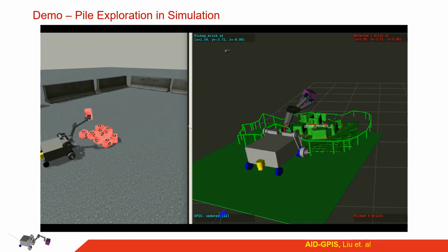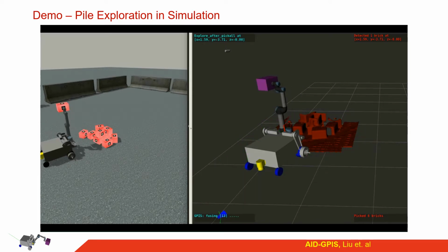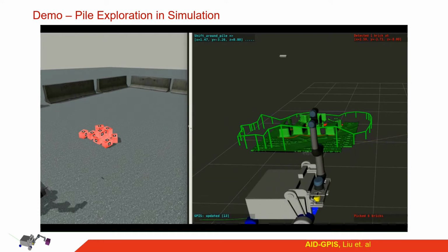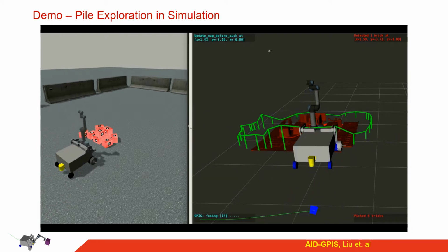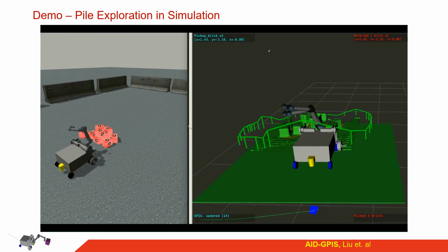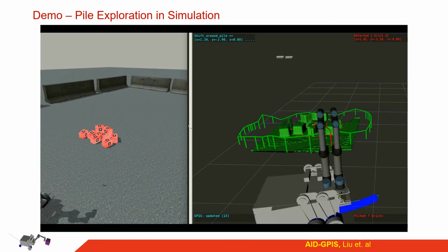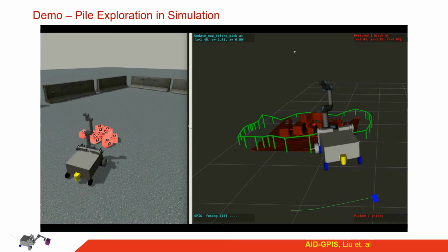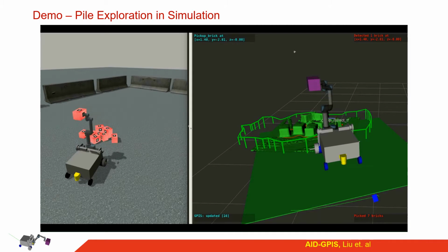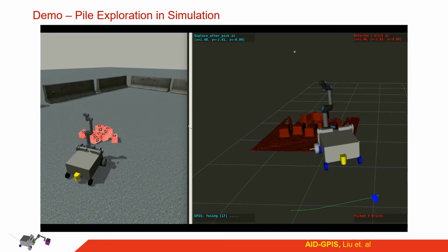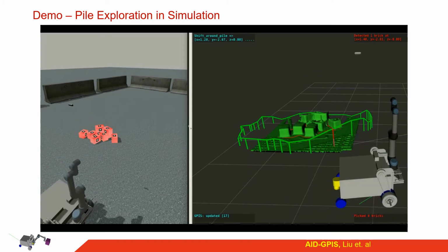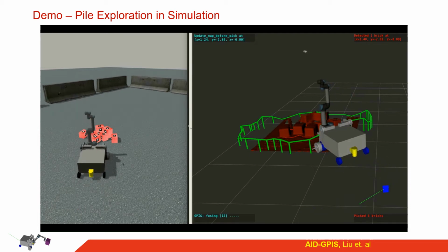Our framework is also about active exploration. From the map, the robot is able to identify possible locations to move to in the next step. These are drawn as green bars in the GUI. The bar heights indicate a utility score, with a maximum bar marked in red color representing the next best view, NBV, for the robot to move to.